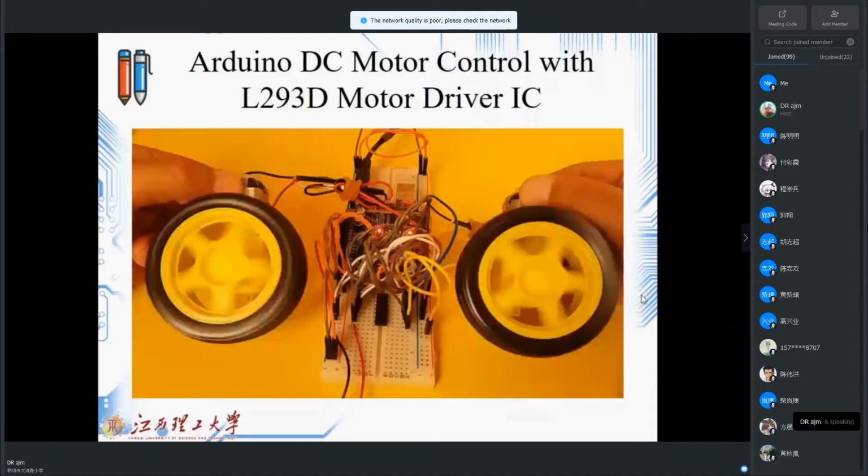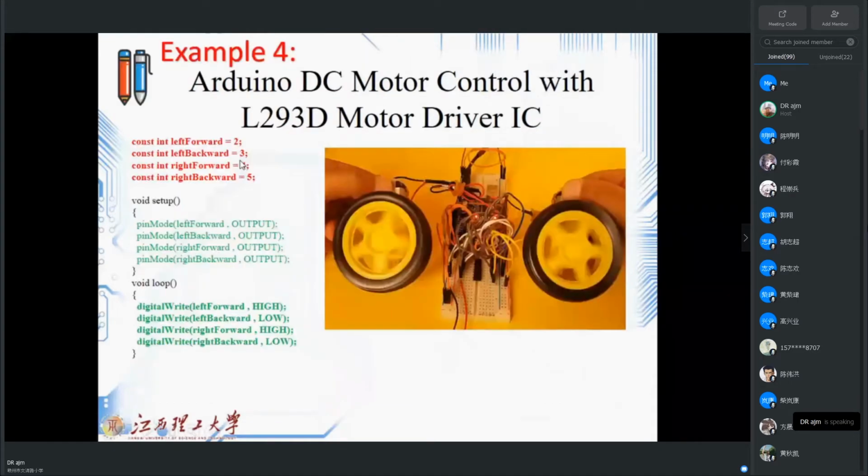Pin numbers 2, 3, 4. And these are the functions, and now this is your task. You should write them. How it will go for left, back, right, back. All of them are based on that table, meaning IN1 and IN2, which one should be high, which one should be low. And then simply you can run the motors right and left.